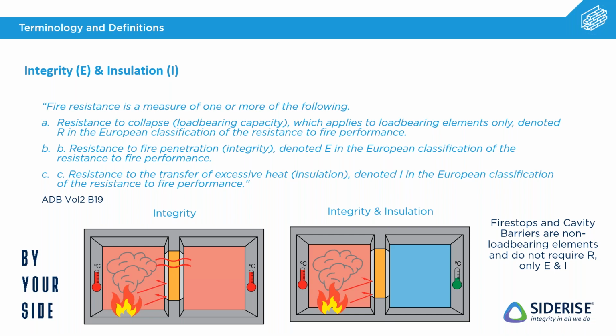Now, in terms of temperatures, to give you an idea, bearing in mind a typical office or residential fire would within 4 or 5 minutes reach temperatures of roughly 1,200 degrees Celsius, which is obviously a horrendously high temperature. In terms of the integrity and insulation, the insulation part, we're making sure within testing that no more than 180 degrees Celsius is ever being transmitted through it. And that's based on one of the lowest temperatures for spontaneous combustion to occur, which typically is paper at about 200 to 230 degrees Celsius.